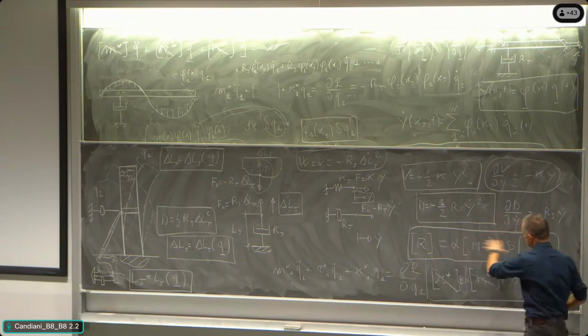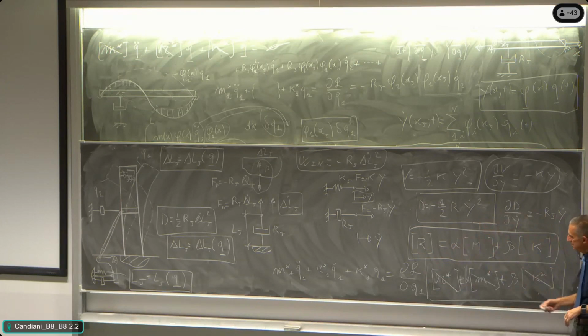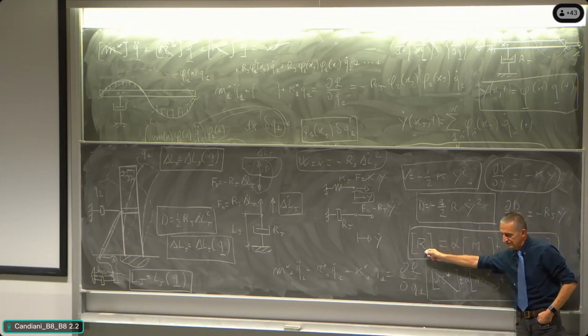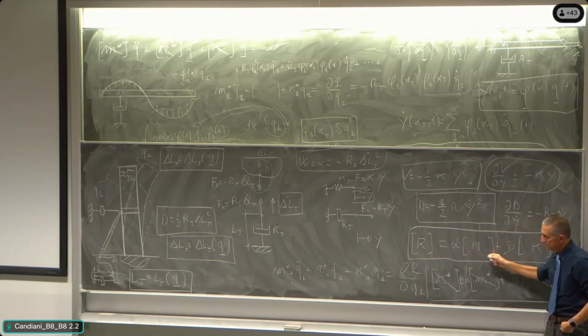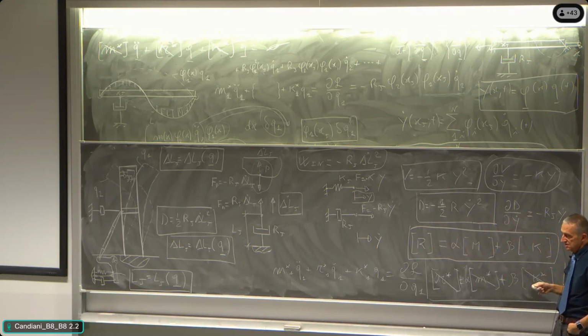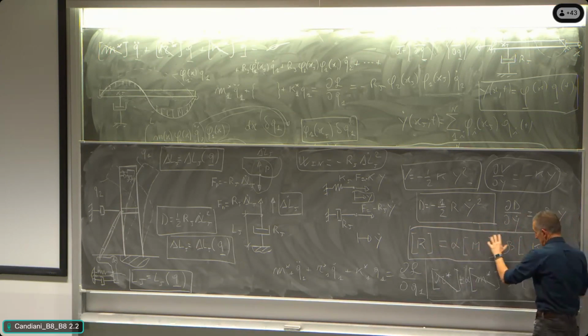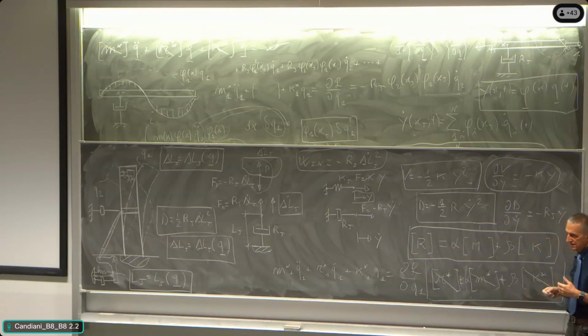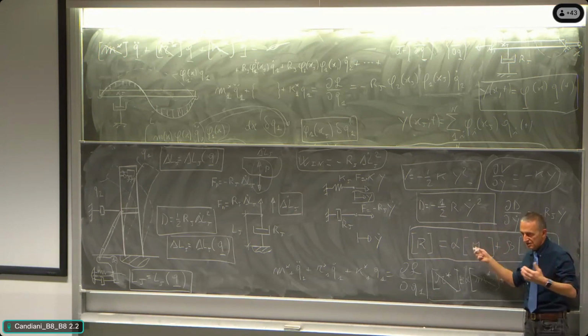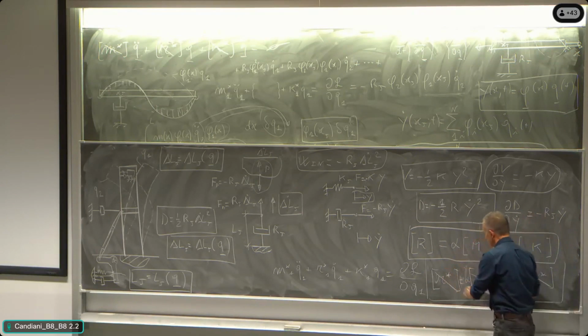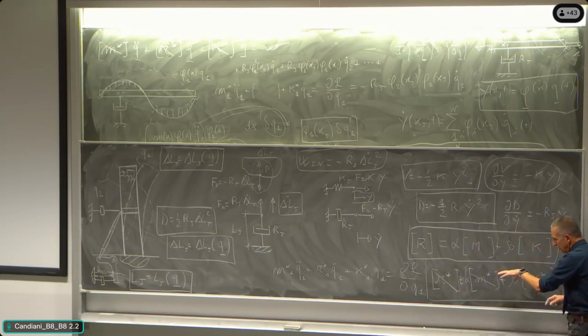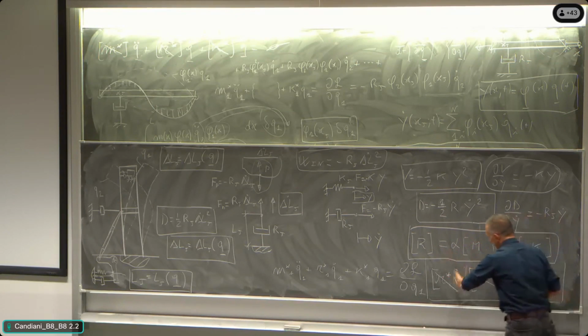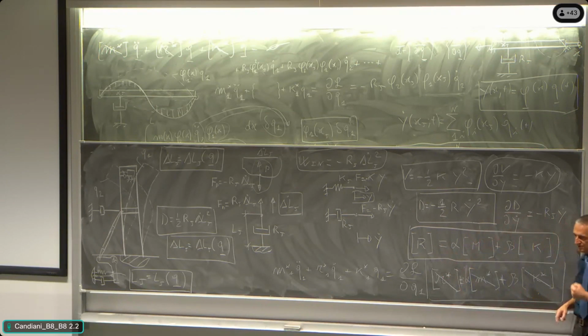If you make a hypothesis like that, being the damping matrix proportional to the mass matrix and to the stiffness matrix, which are made diagonal by the transformation in principal coordinates, you are sure that with this modeling, you will get a diagonal matrix in principal coordinates.